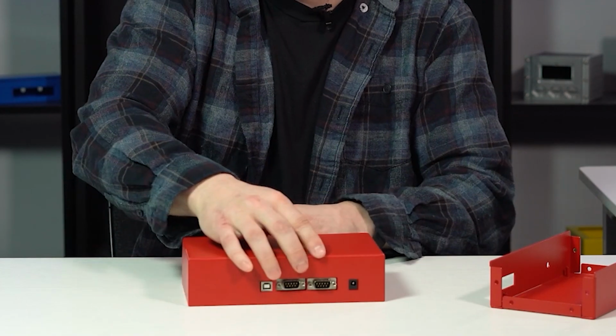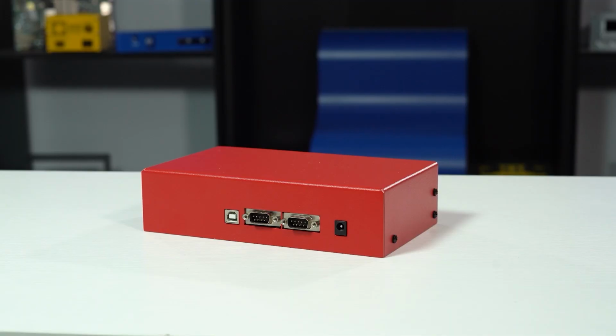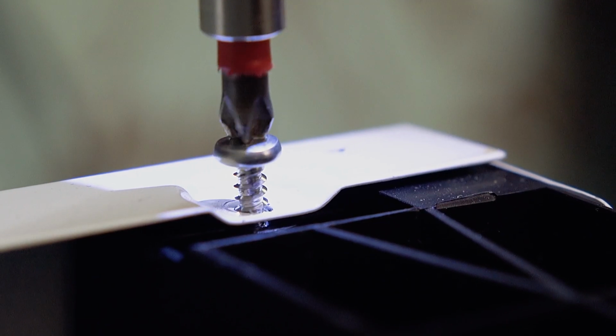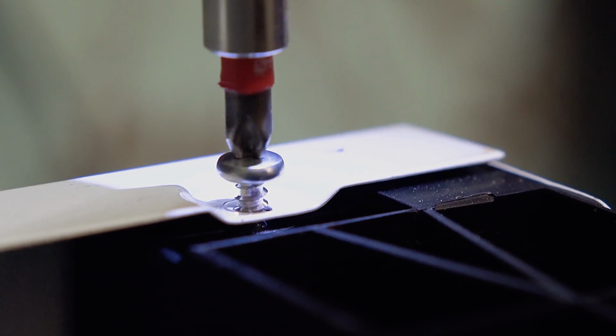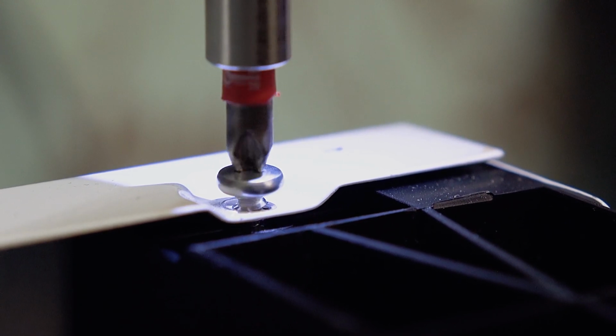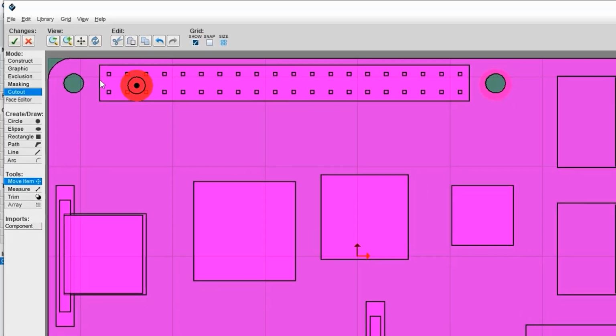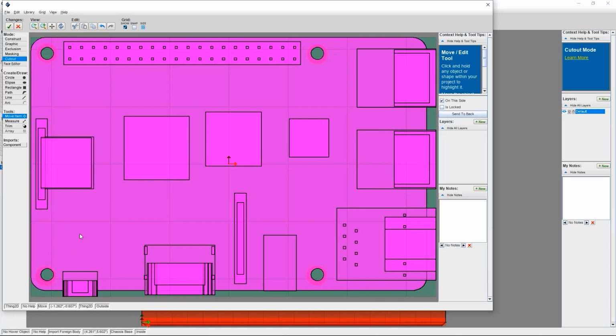So another important thing to remember is to account for the installation of components in real-world conditions. A component may fit perfectly in a 3D model, but might be difficult to install later on. For example, a wrench or screwdriver might not fit in the available space, or it might be hard to hold a component in place while securing it. Providing access for a screwdriver through a flange to reach a screw below can really make installation much easier by keeping the tool straight.